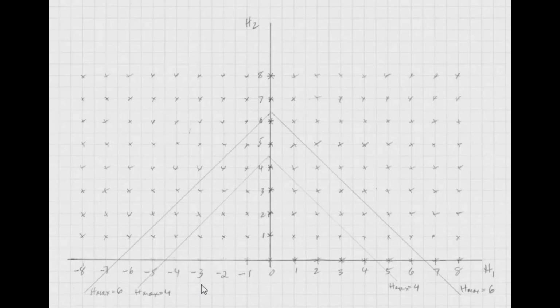Now, in a two-tone problem, it gets a little more complicated. What I'm showing here is the frequency components you get in a two-tone analysis when I've limited the number of F1 harmonics and F2 harmonics to 8 harmonics. So this x-axis is the F1 harmonics, that's 8 here, and the vertical axis is the F2 harmonics, which I call H2, which I've limited to 8 also.